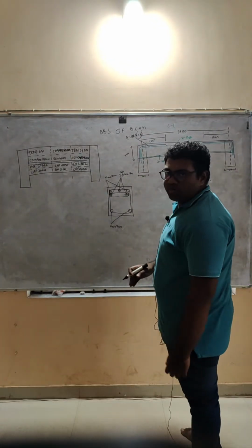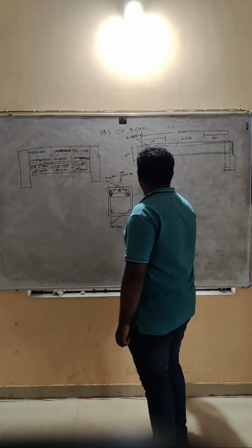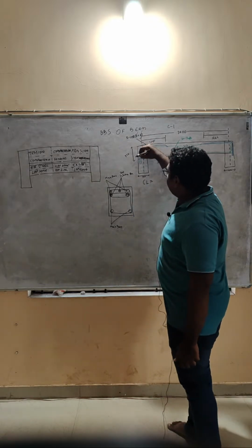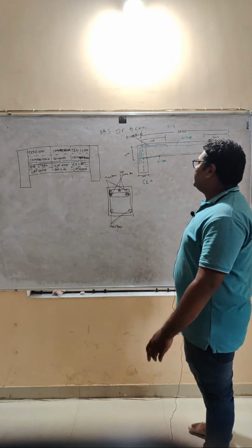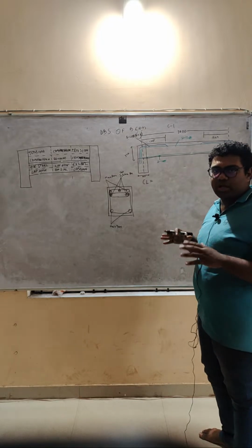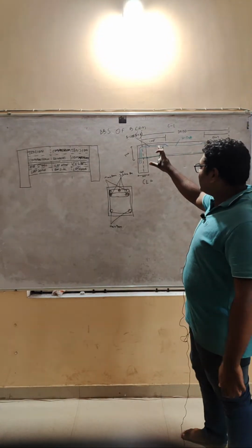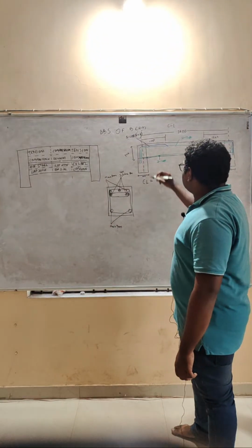We will calculate the cutting length of our beam here. This is case 1. We will take the development length LD, which is 50D. 50D is taken from our IS code. In the IS code, it is given from 46D to 64D, but we are taking 50D here, which is an average of the two. Now we'll proceed to the calculation.